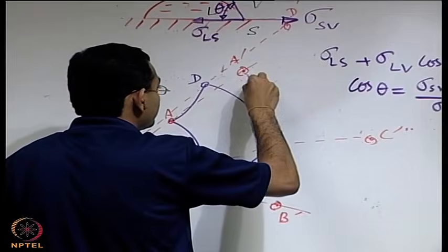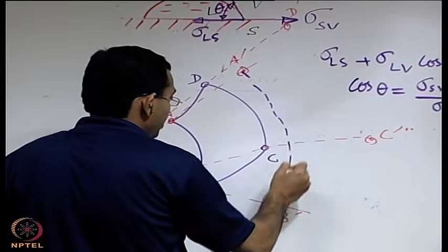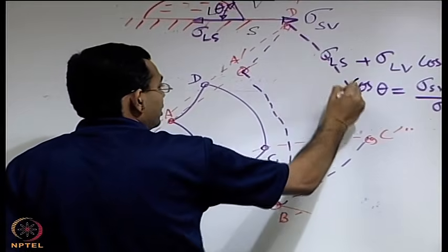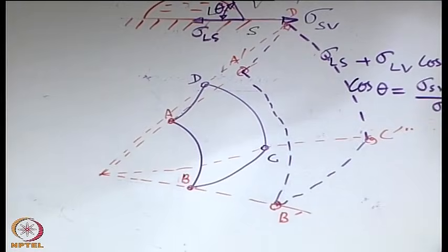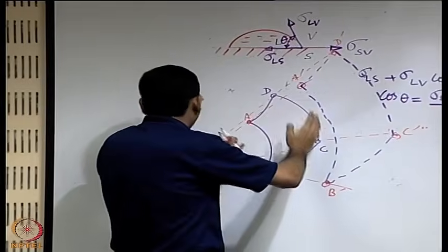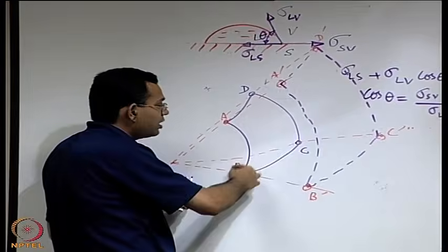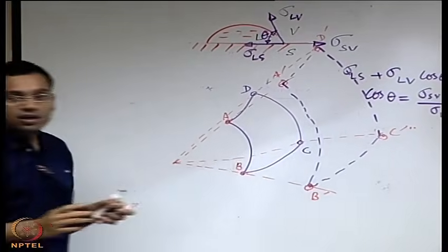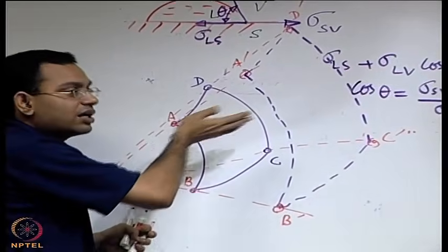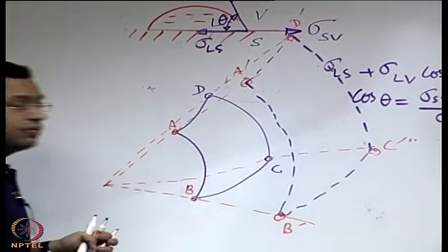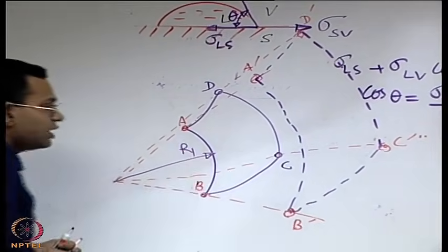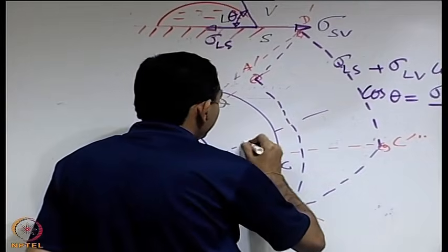So we have a deformed element, but it may be similar in terms of geometrical characteristics, because we have used a sort of stretching and it comes to a new configuration. You can clearly see that this element is made up of two different types of lines: one set of parallel lines, AB and CD, and another set, BC and AD. Therefore, we say it has two different curvatures in two different planes. AB and CD have a particular curvature, and AD and BC have a different curvature. Let us call this radius of curvature R1, and with respect to this R1 there is now a displacement.